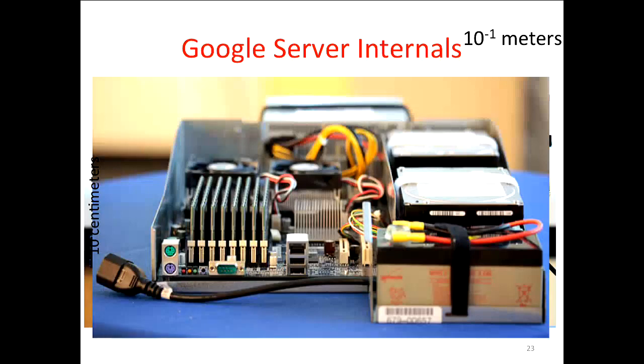The problem is if all of a sudden, Britney Spears gets hot for some reason, everybody's searching, all the Google servers go crazy. All of a sudden, you may want a couple more megawatts to power those important searches people are doing, right? And they can't raise the power consumption. What they do instead is not take it from the grid, but take it from the batteries, right? So they actually use the batteries to smooth out those peaks as well. And this was another reason they had these batteries, more than they probably needed for the battery backup reason. They could actually charge these at off-peak and run them at peak from the battery to stop pulling from the grid, all right? So, at this scale, when you're dealing with tens of megawatts of power consumption, that power engineering is a big factor in data center design.